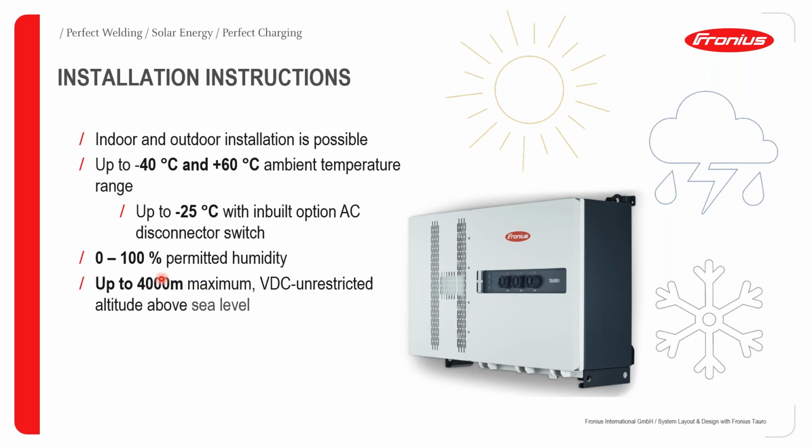Permitted humidity will be up to 100%. And then in terms of the installation altitude, you can go up to 4,000 meters without derating the connection or the input voltage on the DC side.